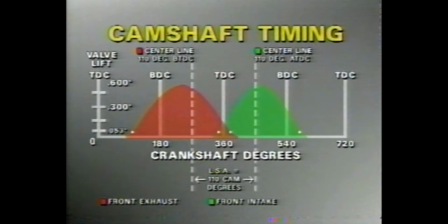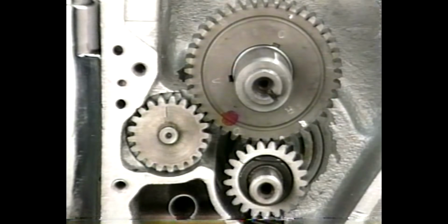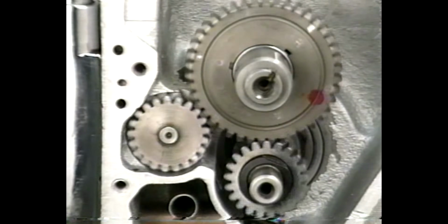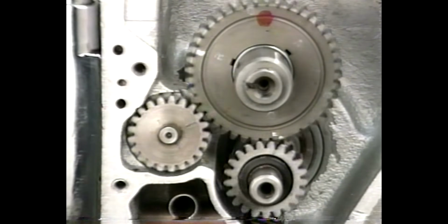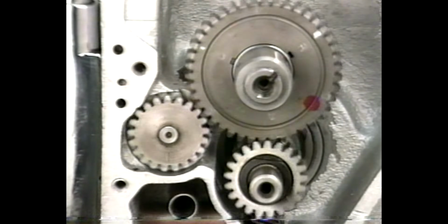In our high-performance engines, we prefer to use cams with lobe separation angles between 100 and 108 degrees, allowing our engines to breathe better and produce maximum torque and horsepower. This compares with stock big twin cams that have a lobe separation angle of about 112 degrees for better idling and emissions control. For this particular 104-inch engine, we have selected an indexable Crane cam, part number 1-1003, which has a lobe separation angle of 110 degrees.